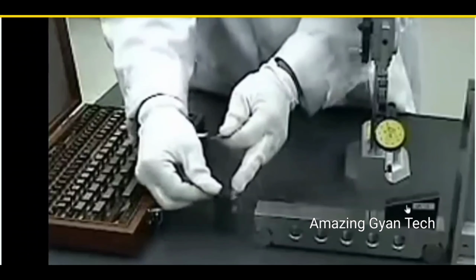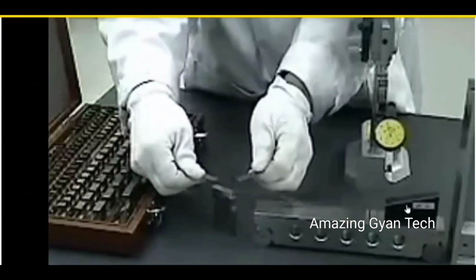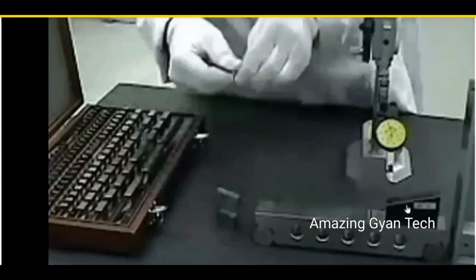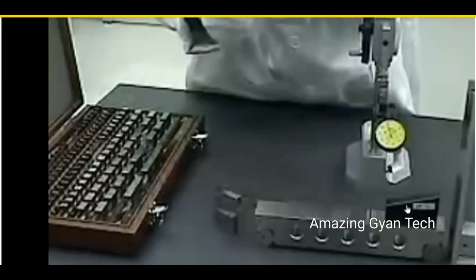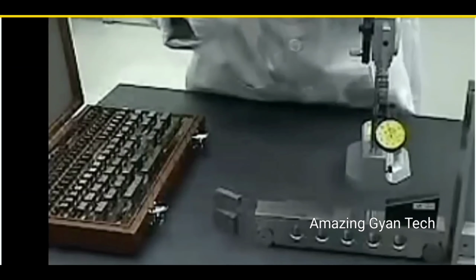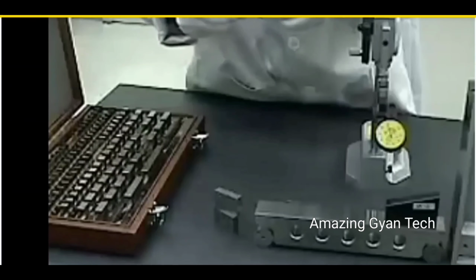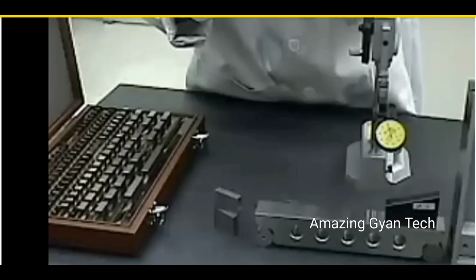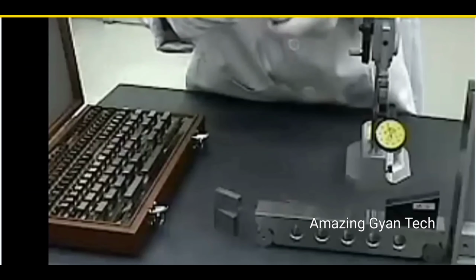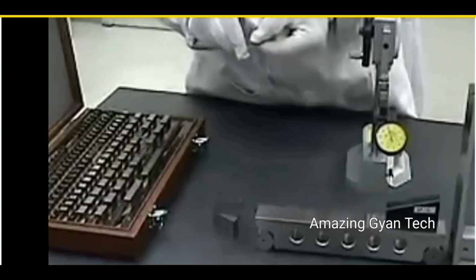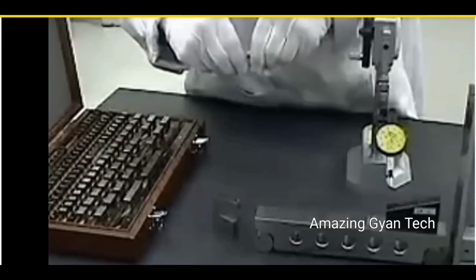So he is taking some slip gauge and replacing it with a suitable size of slip gauges as per the deviation again. So slip gauges are nothing but blocks of standard calibrated thickness. They have a standard thickness that is regularly calibrated and checked to make sure there are no deviations, so that whatever height you are measuring, it will be perfect.